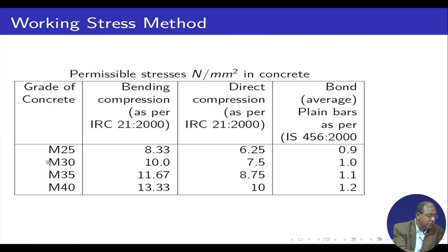Further, we have taken grades from M25 to M40, because for reinforced concrete we generally do not go to M20. So we generally go to M30, M35 or M40. For example, for a residential building we always work within M20, M25 or M30, but for bridges we mainly go for M30, M35, M40. If we go for pre-stress, then we go a little more, M40, M45, like that.